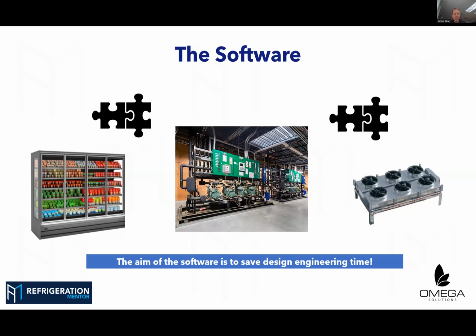Plant within a plant room connected to remote condensers or gas coolers if CO2, but also there might be pre-packaged units like what we're going to concentrate on tonight, so there's no need to size the discharge or liquid drain return because effectively there's an onboard condenser assumed to already be built in.